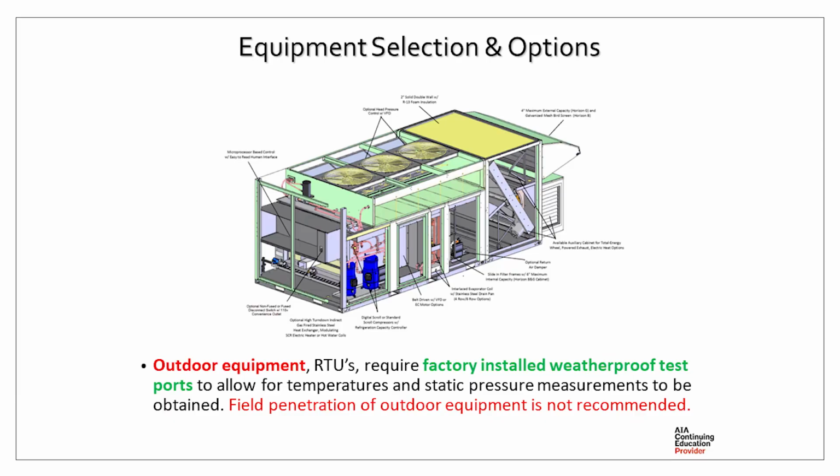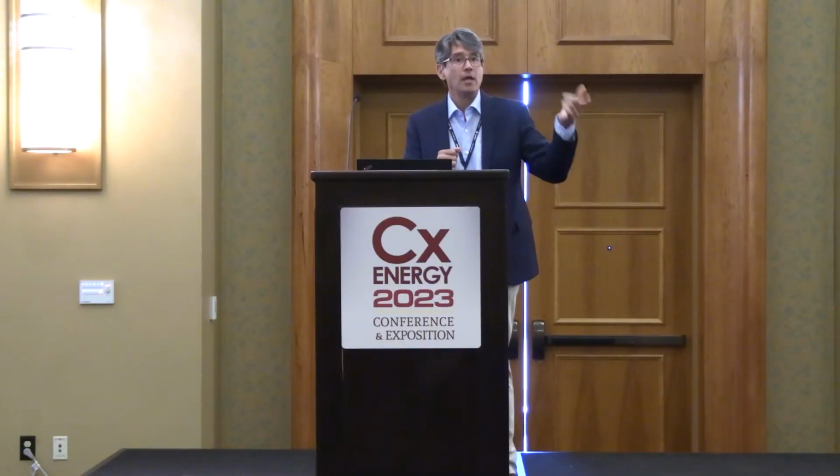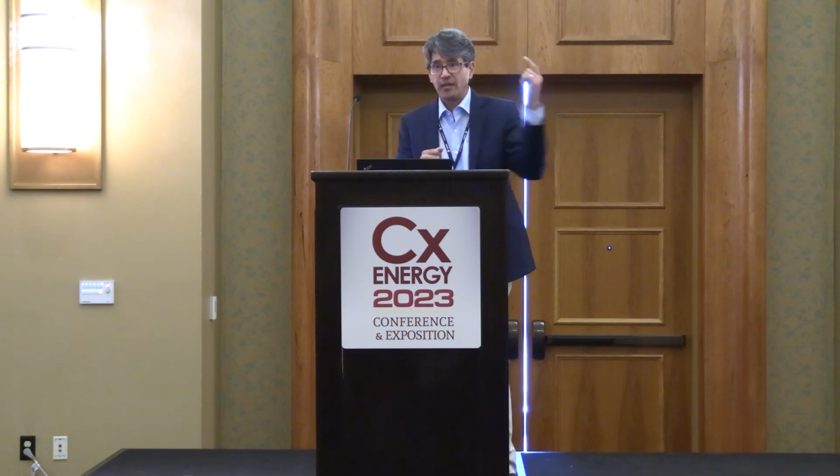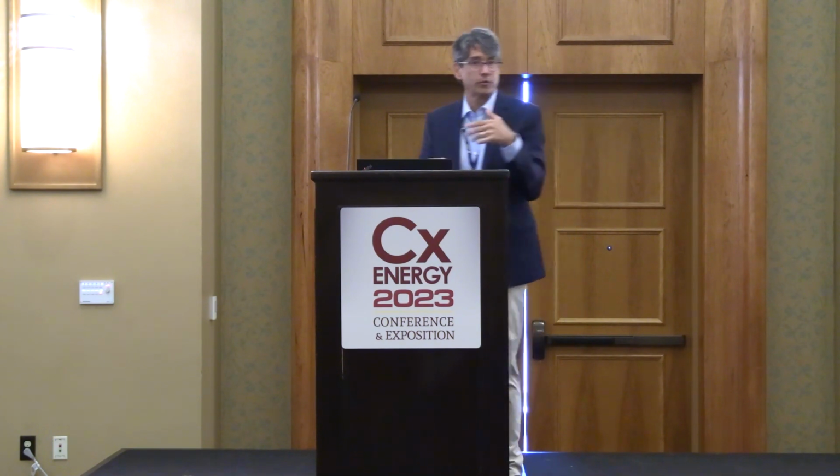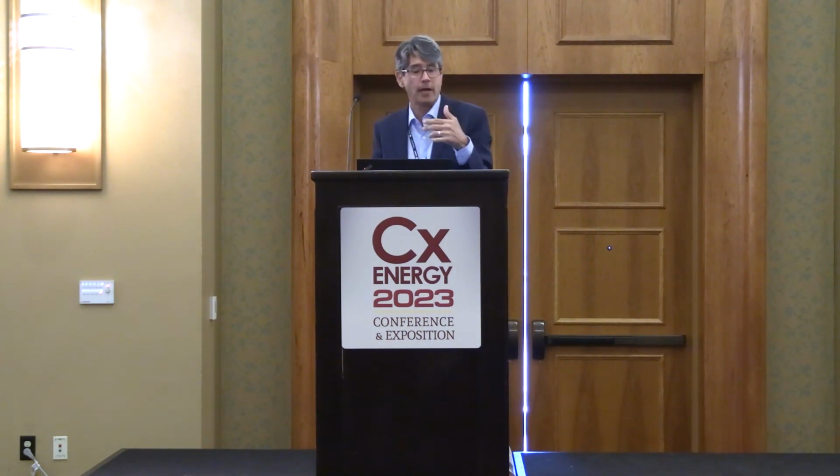One, because penetrating that casing that's going to be sitting outdoors, then plugging that hole back up. The second reason why, we've drilled into too many components. They pack a lot in an external outdoor rooftop unit. Energy recovery units, you've got everything in the world in there between your heat exchanger, DX, if they've got hot water, chilled water. There is a lot going on in that between your exhaust and return path, or exhaust path, and supply paths.